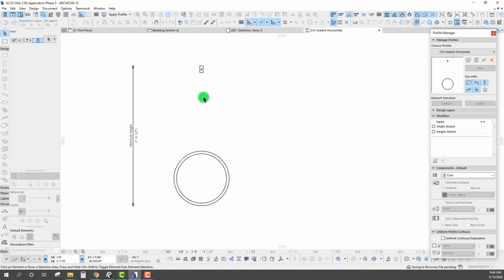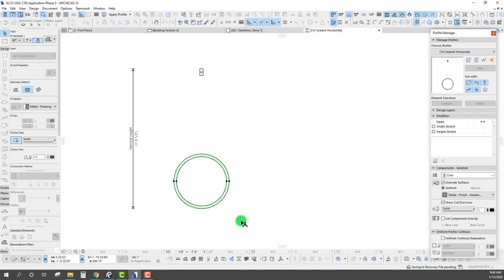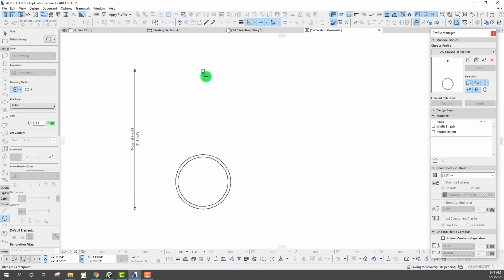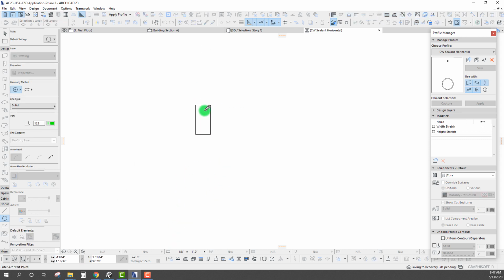We could actually, I think we're in the right orientation as is, but say if we wanted to add in like a cable instead to run directly through this, we could actually do that as well by simply creating a new little radius here. So let's just set this to maybe like 3/8 inch, so we have a 3/4 inch radius.